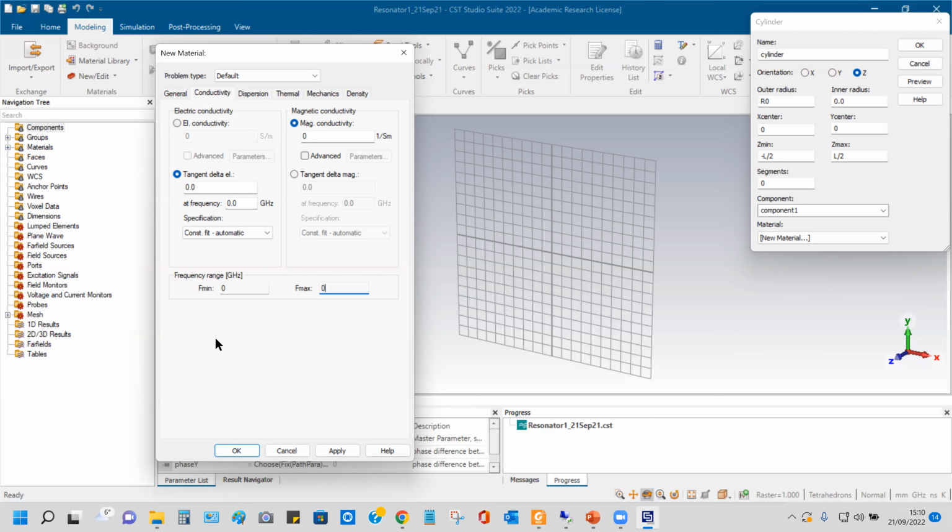While choosing a material, you have to see, okay, I am going to use this XYZ material. Then we have to see how much is the variation in dielectric constant when you work on a metamaterial or something like that. Dielectric constant is crucial there. In any antenna design it is crucial, but a metamaterial is a highly resonant structure, right?